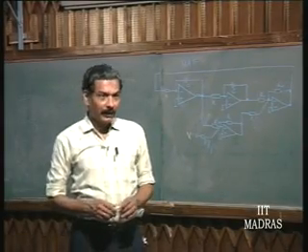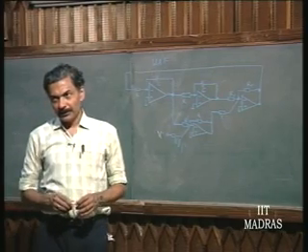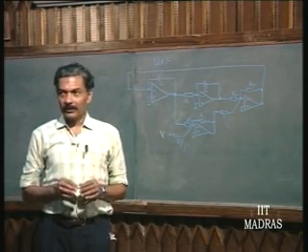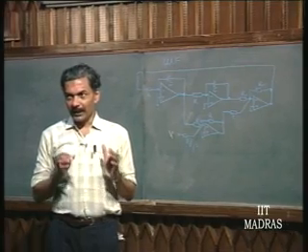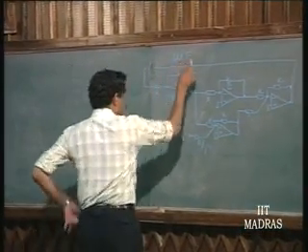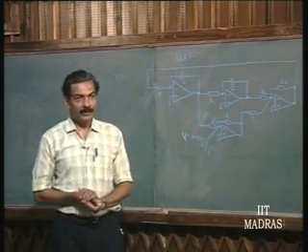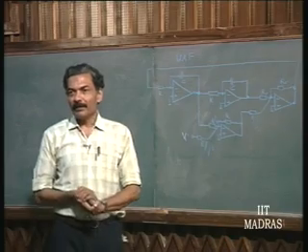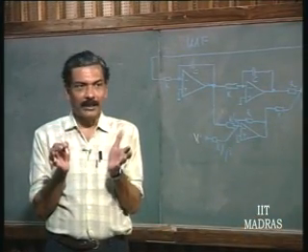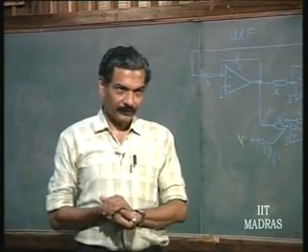Now, we will see another application of this multiplier in a very important block, that is the universal active filter block. Universal active filter blocks are available by themselves as ICs, and these are nowadays being used as VLSI subcells in realizing higher order analog filters.